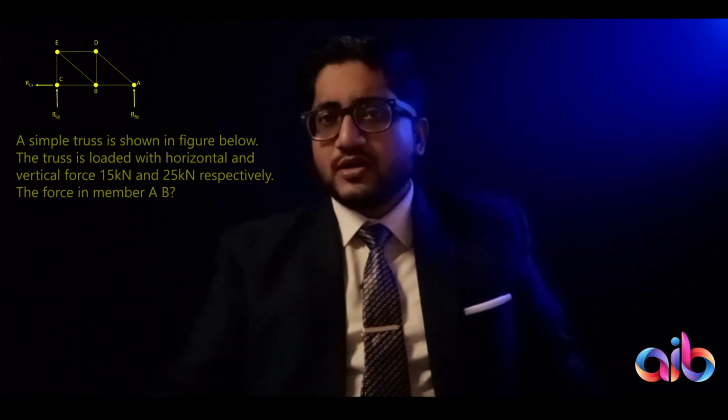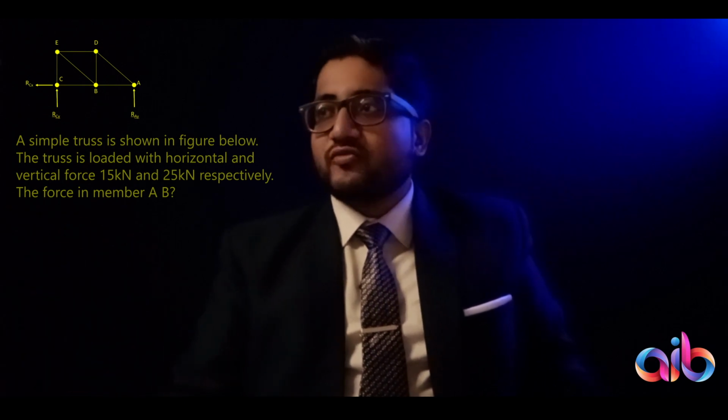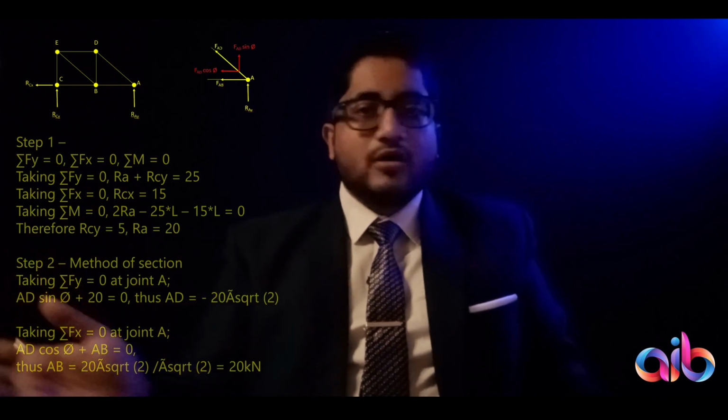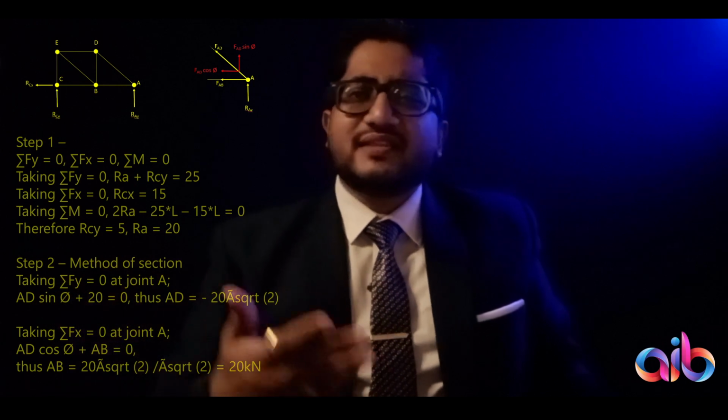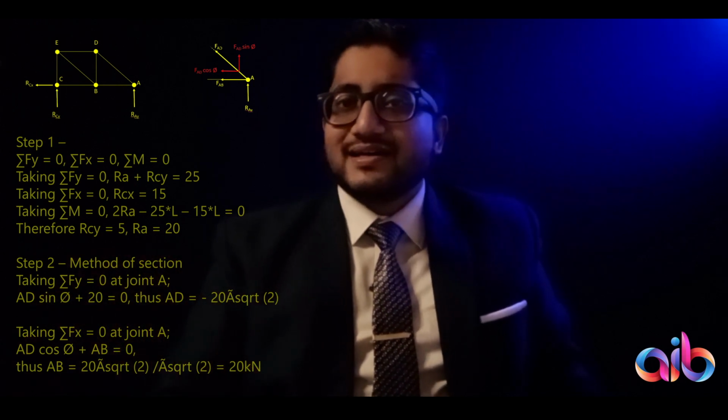Similarly in the x direction also there is no resultant force, it's not moving in one direction on the x axis or the other direction on the other side of the x axis, it is static. This is the concept first that you have to understand, it is statically stable. Next, the third point, the truss is not rotating about a point like a helicopter's blade, so there is no resultant movement also. The summation of all the moments and the deforming forces is 0, it does not rotate by itself. So these are the three major concepts that if you accept and agree with, we can move on to the next level. So summation of forces in the y direction I have considered to be 0, which is fine.